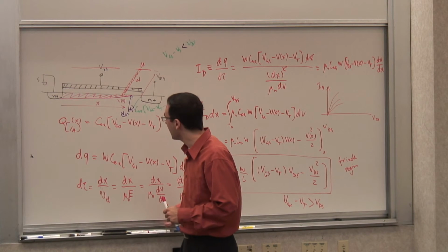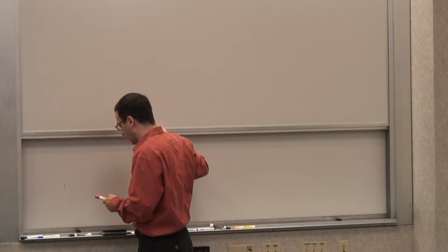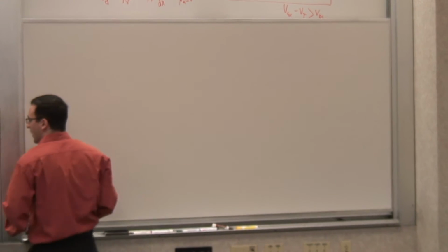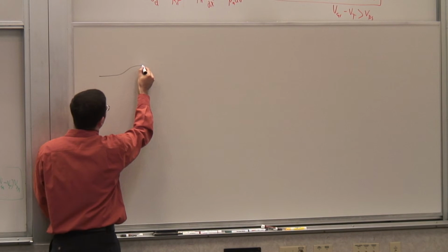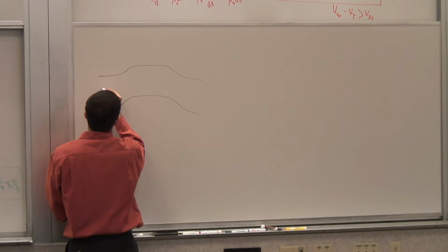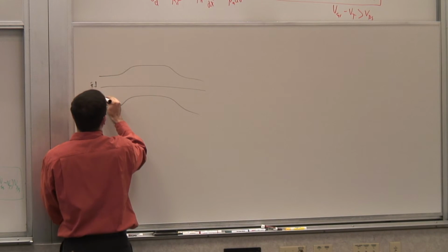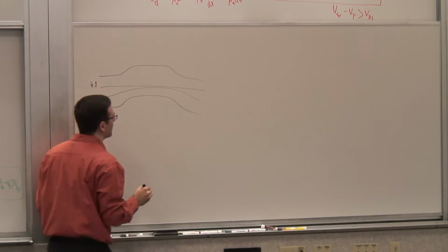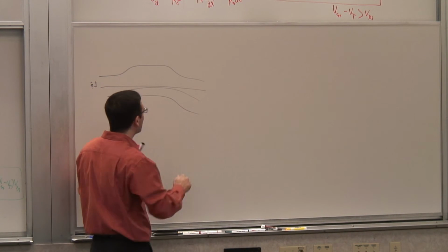Now, in the energy band diagram picture, what that corresponds to is something like this. When we were in the triode region, we said we've lowered the potential barrier, so it kind of looks like that. And then EF and EI kind of remain below that all the time. Now, what I've done here is I apply a larger and larger voltage to VDS.